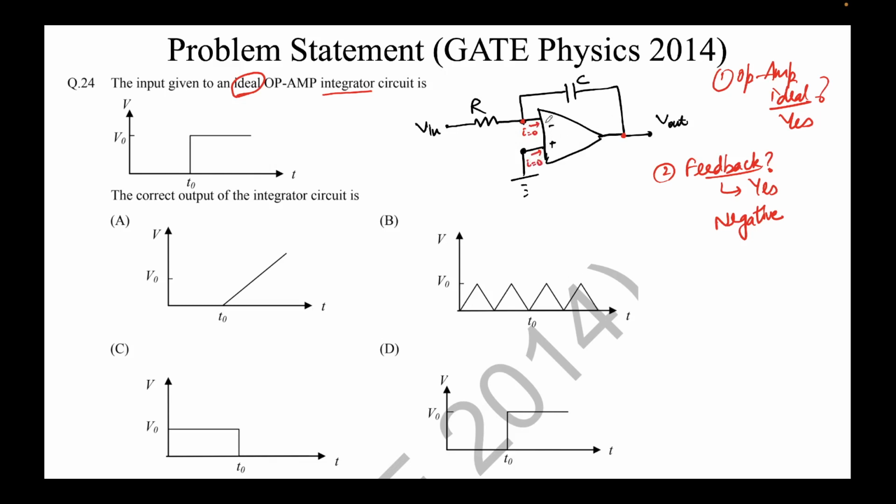Okay. Now, since this is an ideal op-amp, the current going into the inputs of both the inverting and non-inverting terminal would be 0. And recall, we had mentioned that there is an R in, the input impedance. Usually this R in is very high. But let's apply Ohm's law across this impedance. So I can write V plus minus V minus equal to I times R in. Now, since there is no current flowing into the op-amp, I can write V plus minus V minus equal to 0. This gives V plus equal to V minus. This condition is called a virtual short.